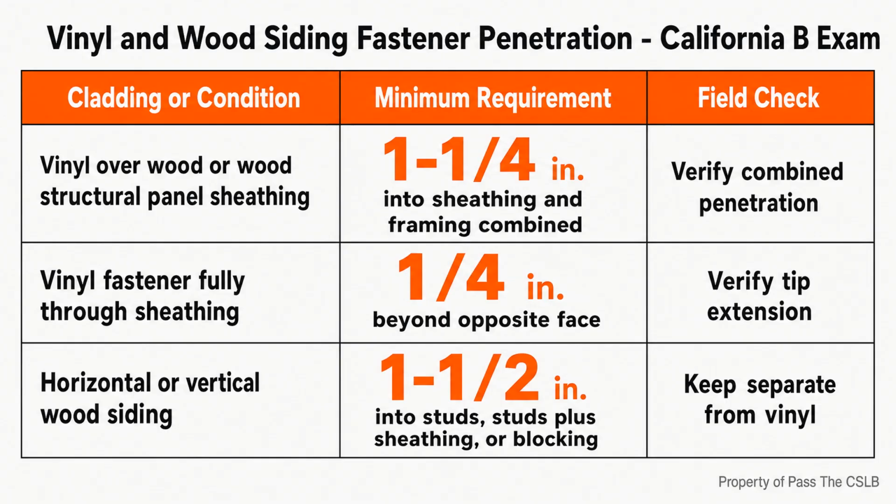Consider a hypothetical remodel where a crew installs a projecting wood band and plans to rely on a bead of exterior sealant across the top. If the required continuous flashing is missing, the sealant does not create the same shingle-fashion path behind the siding. Sealant may be part of an approved detail, but it should not be used as a substitute for a flashing component the detail requires. I also look at sequencing before the siding hides the work.